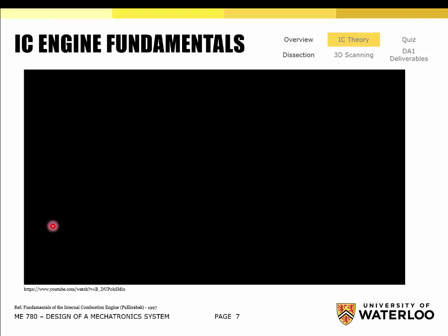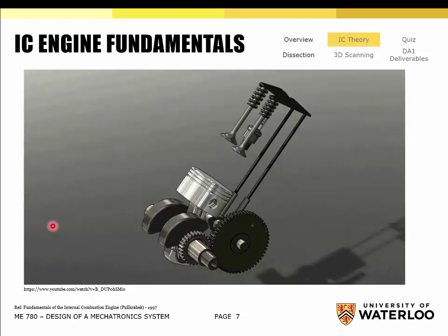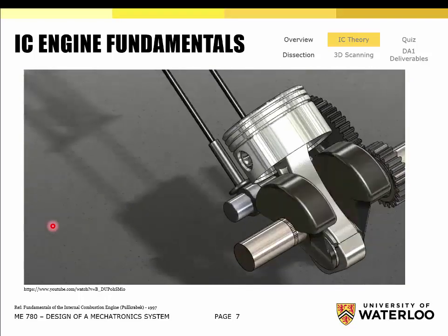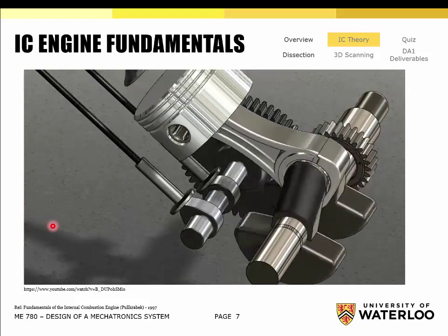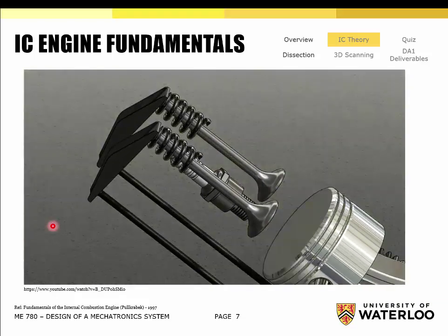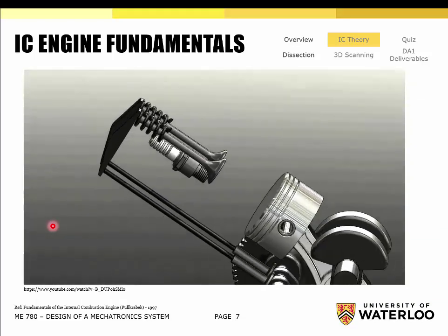So the camshaft needs to operate at a lower speed. Yes. You want it at exactly half the speed through the cycle with the intake and exhaust? Yes, exactly. Because of the thermodynamic cycle, if you count it, it takes 4 strokes of this piston to see each of these valves open and close once. Okay, that's one complete cycle because it's a 4-cycle engine.